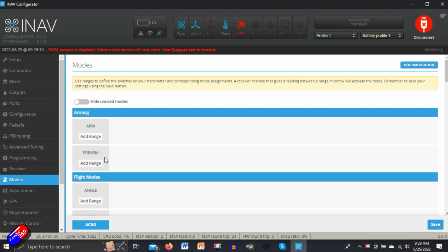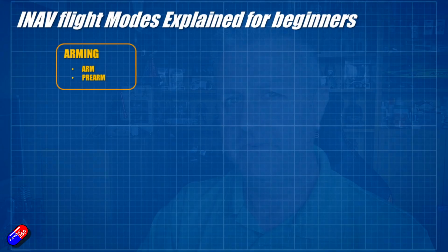Multi-rotor, maybe it's a little bit more difficult, because with a lot of multi-rotors, when you arm the multi-rotor, by default the props will start spinning straight away. So you don't want to accidentally hit that switch on the radio as you're carrying your multi-rotor to the flight line. Things will get interesting. But for a fixed wing model, the arming switch is normally enough.